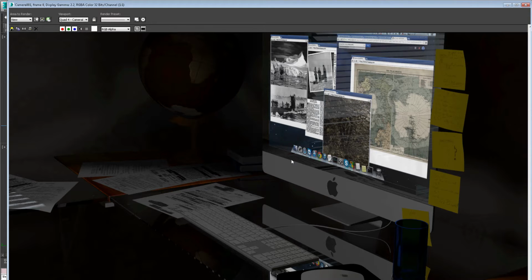Okay. As you can see in here, the caustics on the wall look good. And that's because, again, bringing up the photons to 1000 and changing the blur factor between the photons to Gauss help blur it and create a better look. And of course, increasing the final gather gave me an overall better look as well.